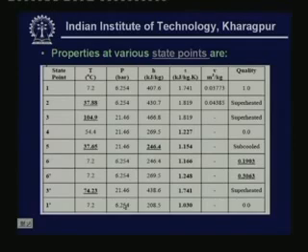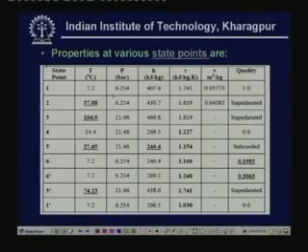State point 1, as I have already told you, is the exit of the evaporator, which is a dry saturated vapor at 7.2 degrees centigrade. At this point we find the saturation pressure to be 6.254 bar, and the quality, as you know, is 1. So, we give these two as the input and we find the rest of the properties. We find the pressure, the enthalpy 407.6, entropy 1.741, and specific volume 0.03773.